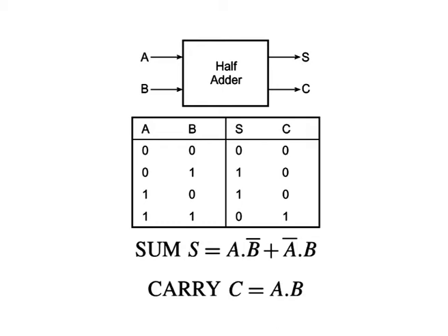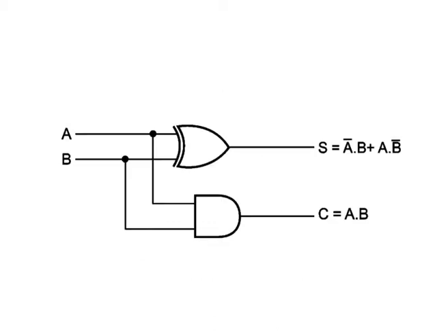However, these two expressions can certainly be represented in different forms using various laws and theorems of Boolean algebra, to illustrate the flexibility that the designer has in hardware implementing as simple a combinational function as that of the half adder. We have learnt in earlier lectures on Boolean algebra how various logic gates can be implemented in the form of either only NAND gates or NOR gates.